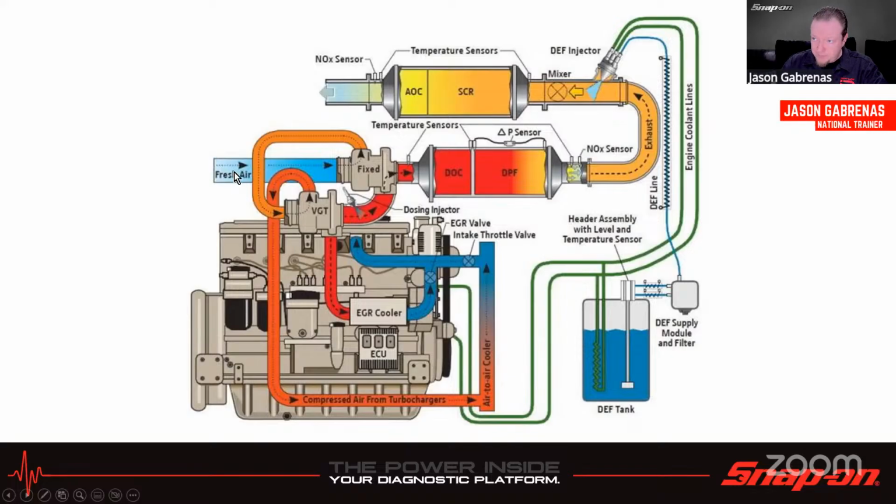So if we go from the beginning, we start off with fresh air coming through the turbo, and of course that gets run by the exhaust. We also have the variable geometry turbo, which can bring air back in through the cooler. We have an EGR valve and intake throttle valve. If it has an EGR valve, it does have a throttle valve on it. Then we have the oxidation catalyst, the DPF, which is going to have a pressure sensor on either side, a differential pressure sensor. So that's going to compare the inlet pressure to the outlet pressure to tell whether or not it's clogged. We also have the SCR down here, the selective catalyst reduction.